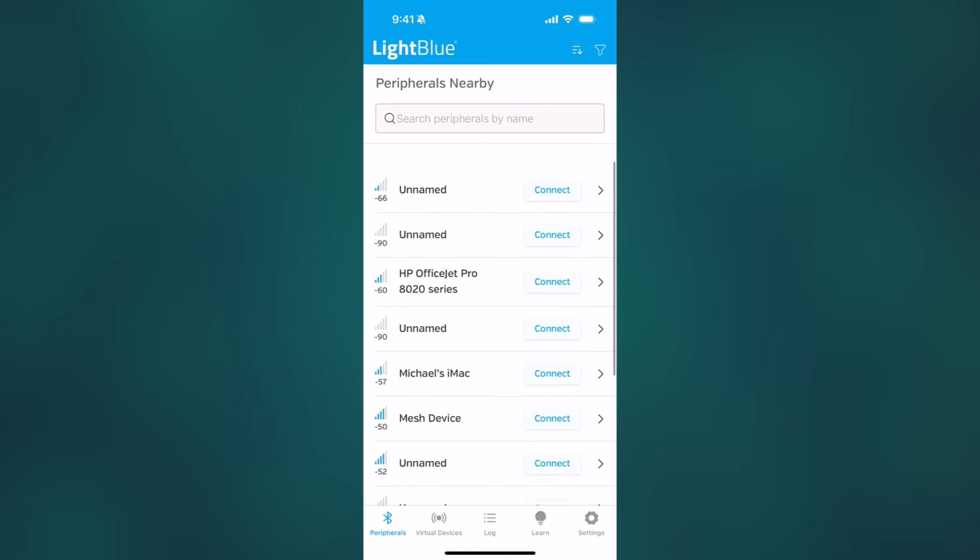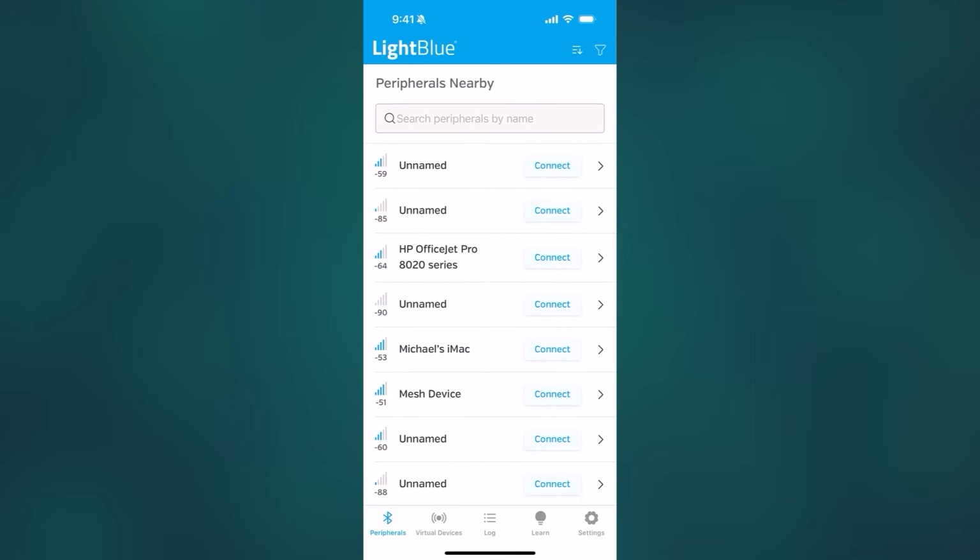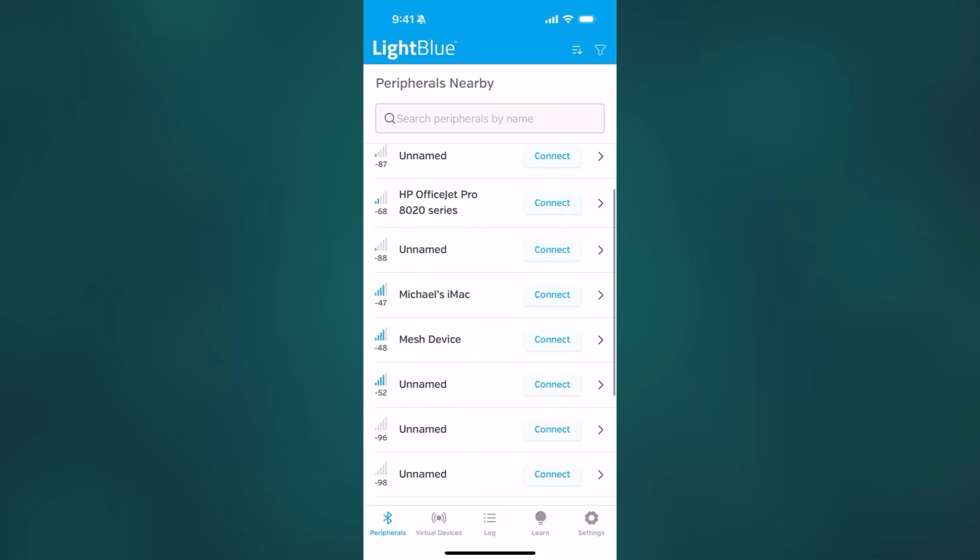What's going on? Well, here's the deal. What happens when your device gets connected to and then disconnected is that the advertising that we started automatically stops. Actually, as soon as a client connects is when the advertising stops. So if we want to continue to advertise to other devices out there, or to advertise again after one of the devices disconnects, we need to start the advertising again.